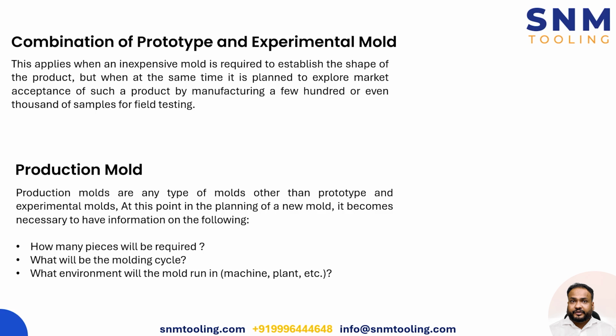At the same time, I can also test that experimental mold, or the combination mold, for shrinkage, because shrinkage is something which gives variable results with time, right? So if a few hundred samples are manufactured, out of that sample lot, say 30 samples, a capability study can be done, and CP, CPK can be found and checked to know if the process is capable and repeatable, right?